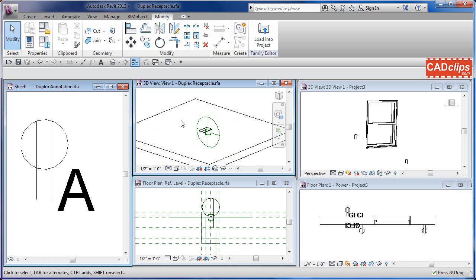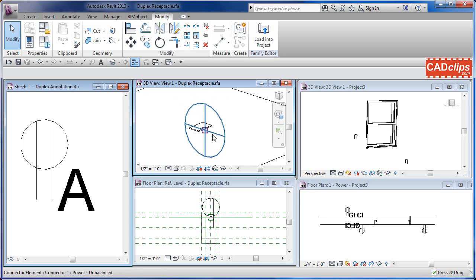By doing so, you can take it and customize the stuff the way you really want. Once you totally understand how this all works, then maybe you can create one from the ground up. But it's always highly recommended in the beginning, and even to date, I still take a lot of the out-of-the-box families, mainly MEP, and then just make those modifications. So inside of here, I'm going to go back to my wireframe.